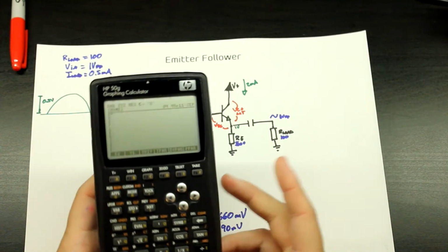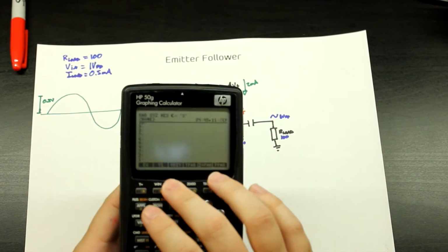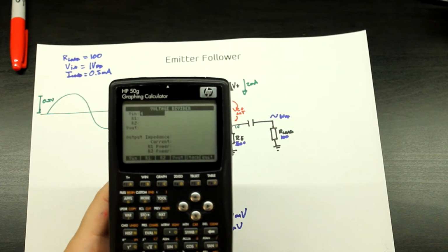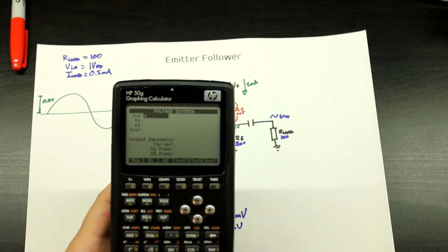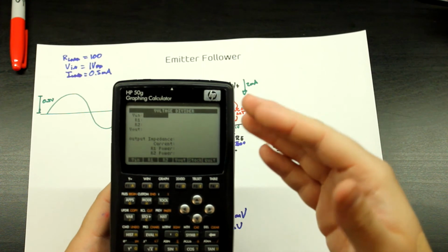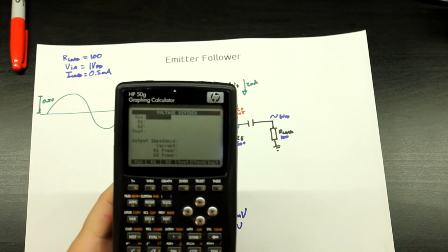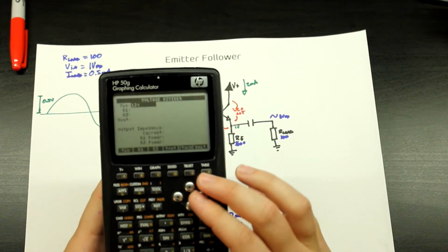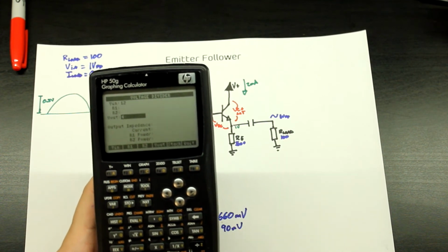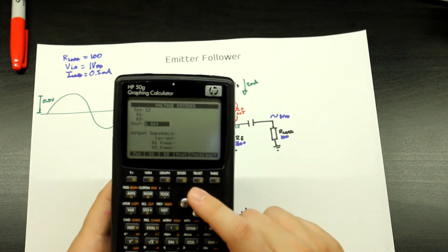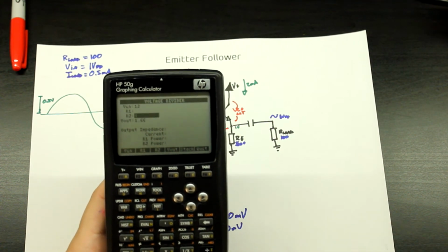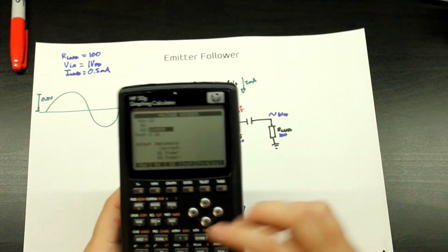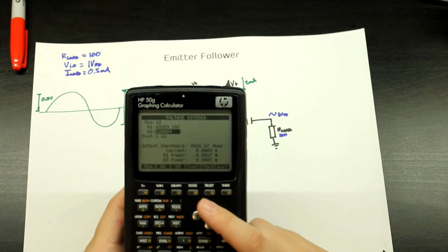So here in my calculator, I just wrote a little program that lets me calculate voltage dividers. This is so that I don't have to memorize all the permutations of the formula. It's very simple. Let's just say that we have a voltage input of 12 volts. We want 1.66 volts out. And just so we have something to work with, let's say we want 10K for R2. So we calculate R1 and it gives us